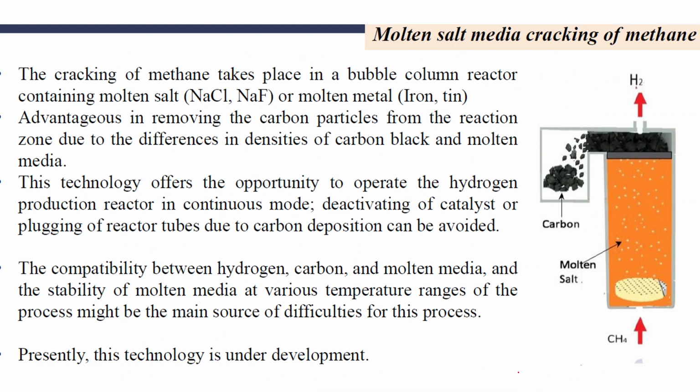And the last technique is molten salt media cracking of methane. In this, a packed bed is taken in which molten salts are filled, and methane is introduced here. Methane gets decomposed by coming in contact with this hot molten salt bed.